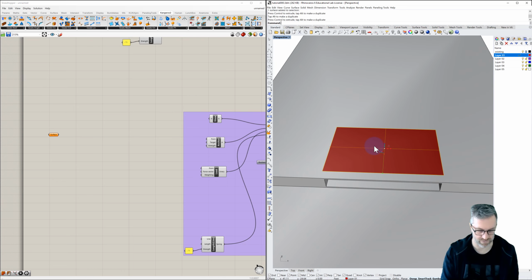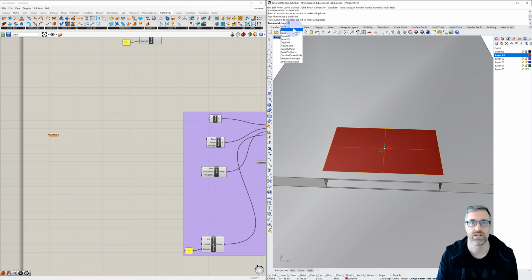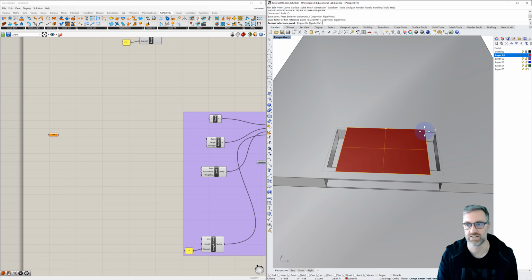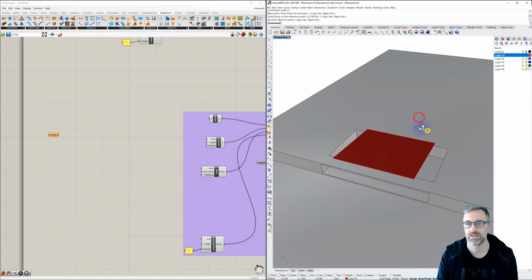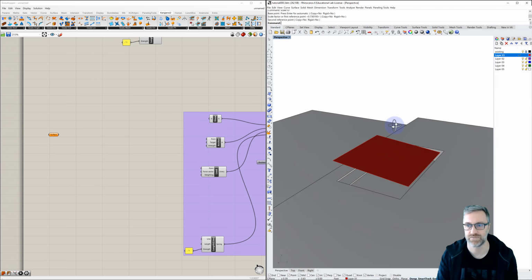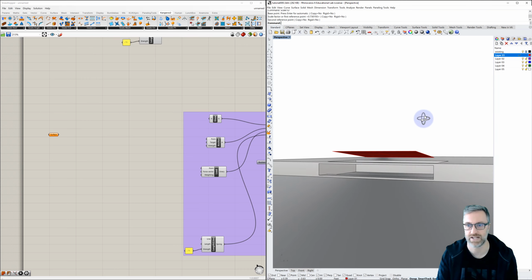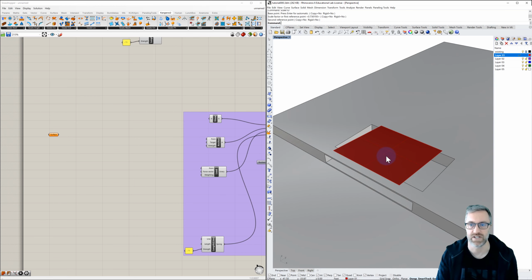And maybe the last thing that I'll do is just scale 1D in plan. If I select it at its midpoint, I can pull it in on the sides. So now we just have a rotated flat plane up on the top. Let's set the surface container to that one element. I'll then hide that surface, and now we have the Grasshopper representation of that.